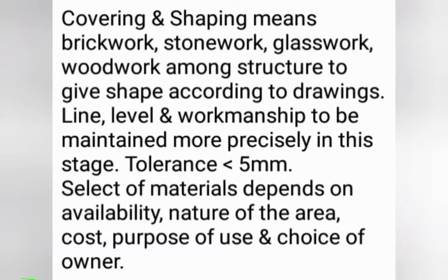All joints should be 10 mm to 15 mm. If needed, wire mesh is to be provided. Various types of cracks occur due to bad workmanship, so care should be taken. In stonework, more precision is to be taken as making sized pieces is more costly. The type of stone is also to be chosen before this work.